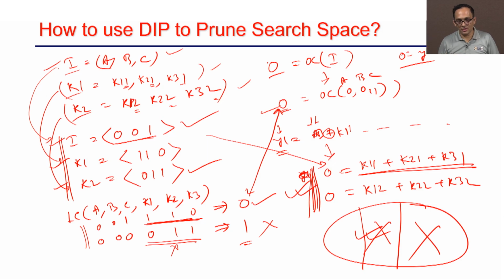These are the wrong keys. Then the only key remaining is here. Again I will get two such equations, and these two equations I am going to add to the original SAT formulation and I will call it again. This way it is not removing only one key, rather it will remove a set of keys in every iteration, and finally I will end up having the correct key.